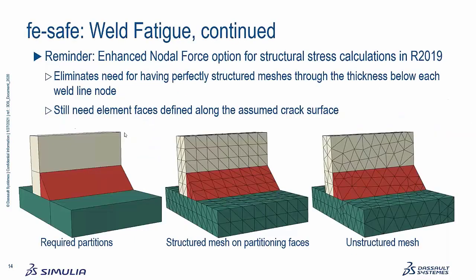It's more automated. I do want to remind people of something we released over a year ago, and this enhanced nodal force option. With the basic nodal force method, you have to have these perfectly structured meshes. Okay, where under the weld line node, you had to have the nodes lined up beautifully below it, or else you could turn on a lot of smoothing.